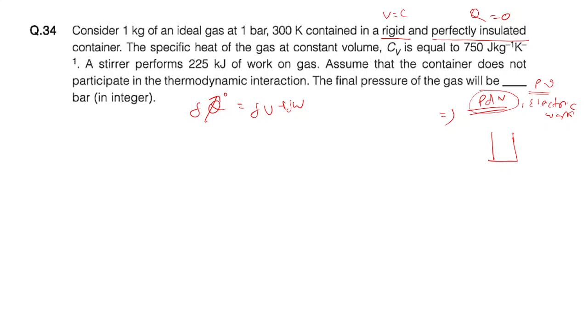Good. And then electric work and stirrer work. Electric work means I square R T, right? Yes, sir. That heating will happen, but because this is not reversible, they come in a separate category. Somewhere there would be a resistor, and it heats. So don't keep that in the heat part. Put that in the work part, right? Those mistakes you may commit, so keep that in mind. So electric work and stirrer work.